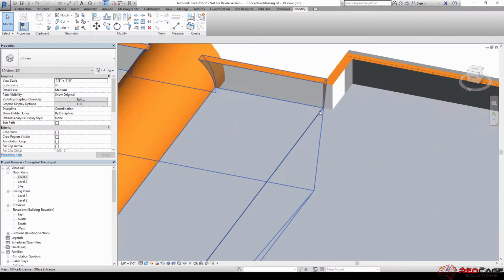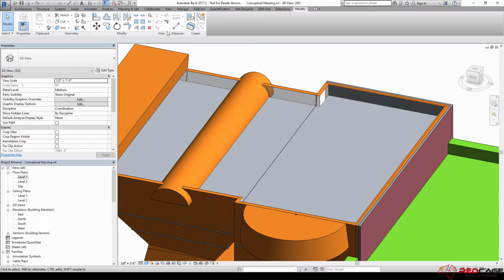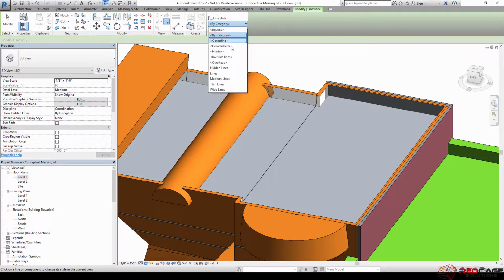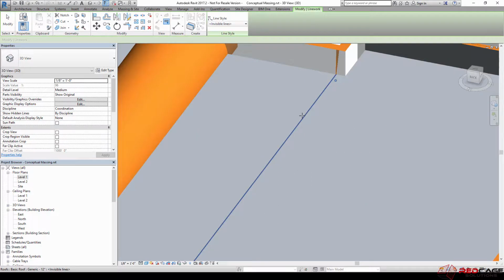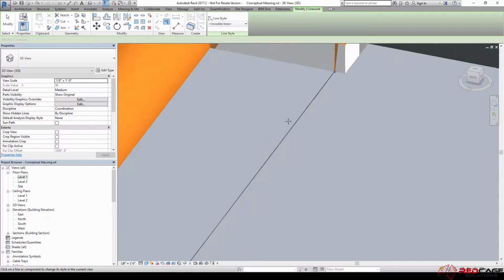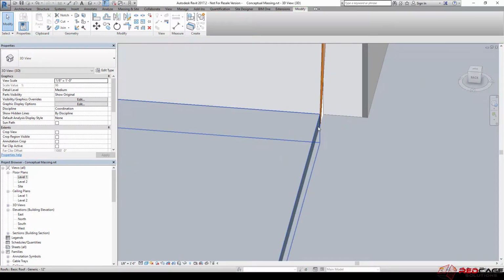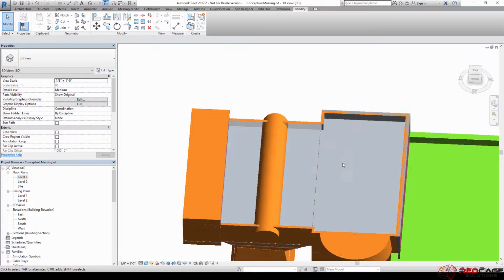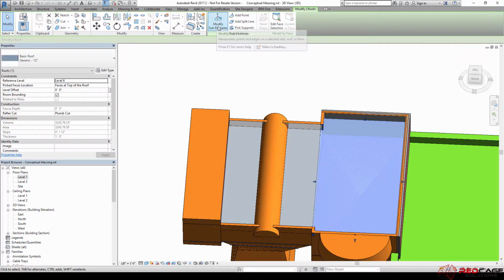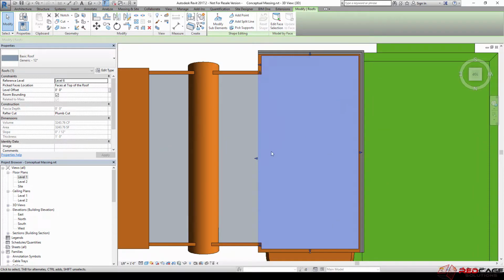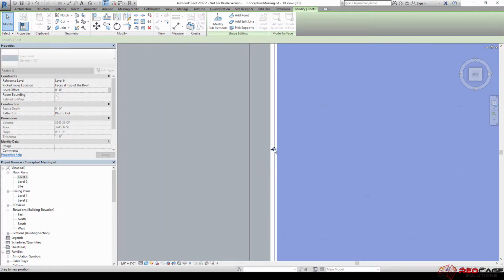Okay, so now I've got two roofs. They are joined, but you know, you might want to get rid of that line work. So there's this tool here as well, line work. I mean, this is not at presentation level, but just to hide that one line quick, we can just use our line work tool and click on that a couple times and it should go away. Almost there. We're grabbing a whole lot of lines. Oh, I think there's a small gap. Yeah, there's that small gap which isn't letting us do it. So not a big deal. We can grab this one, and again, we can go in and modify that as well. So just taking that one grip, we'll move that over.